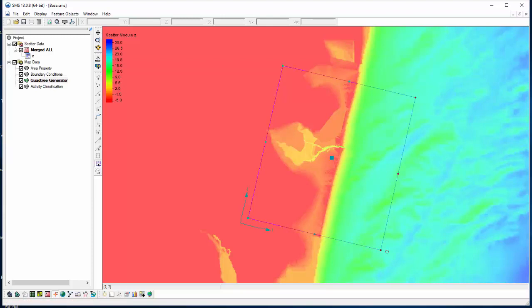In the dialogue or the presentation, I wrote down some numbers, and I'll probably go back and use that. But for now, you can just play around with this and get this approximate. You want to have a significant amount of room on the lateral edges so that you're not interfering, if there are any lateral issues on your boundary, that it does not affect your inlet. So you just want enough distance there. It doesn't have to be this large. It could be a little bit smaller depending on what you want.